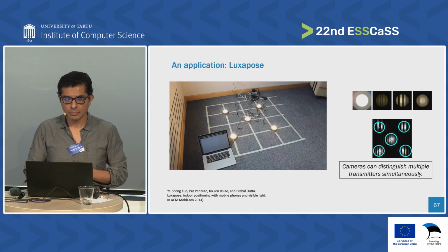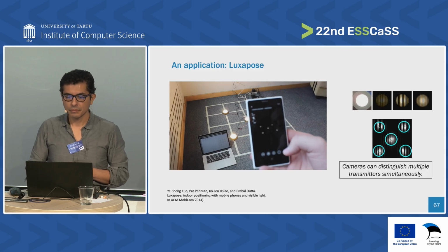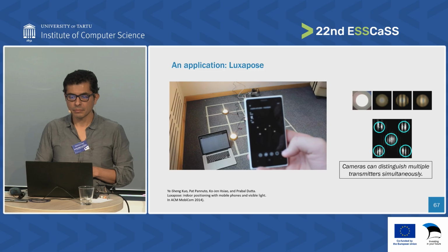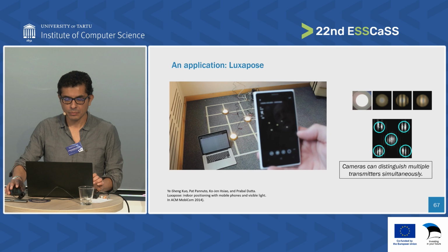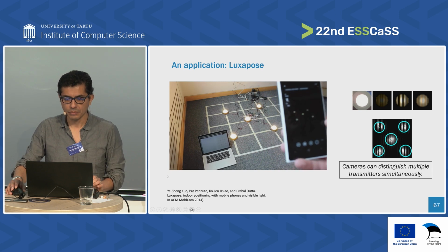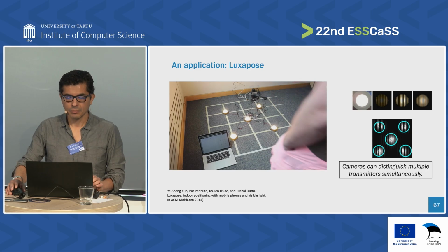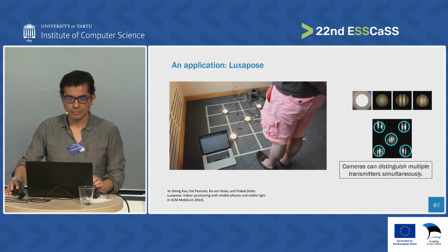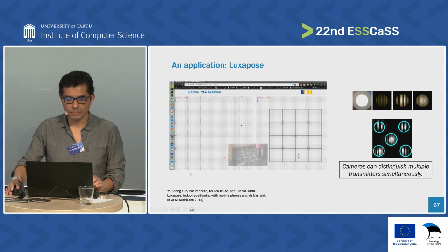Demo participants will all be given a mobile phone running our application. While the application is running, it continuously takes pictures. As you observe as it's taking pictures with a very short exposure, it is actually capable of capturing the fact that each of these LEDs is not stationary, rather each one is running a 50% duty cycle with a different frequency component. This allows us to label each of the LEDs and perform trilateration, such that when the user is near the testbed or walking through the testbed, arrows indicating the user's immediate position and orientation as they walk around the space show up in real time on the display. The user will be able to use both the front and...